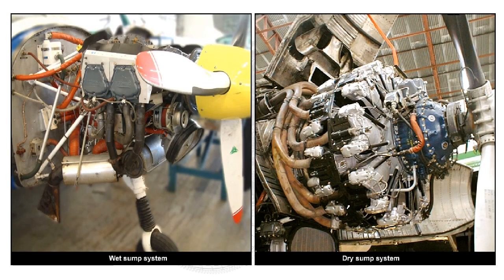There are 2 lubrication systems in common use in aircraft engines. They are the wet sump and dry sump systems. The system used is normally dependent on the power output of the engine and the role of the aircraft. The principle of lubrication of the engine is the same whichever system is used. The main difference between the two systems being the method which is used to store the supply of oil.